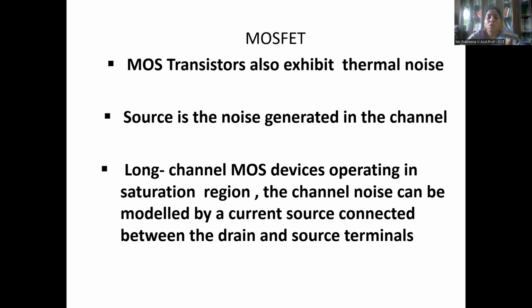Generally, MOS transistors also exhibit thermal noise, which is generated by the random motion of charge carriers in the channel region. For a long channel MOSFET operating in the saturation region, this channel noise is modeled as a noise current source connected between the drain and source terminals.